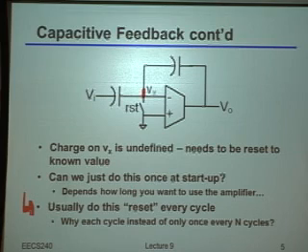So you don't have any residual effects from a last sample? Okay, you said so that I don't have any residual effects from the last sample. That is true, but let me be a little bit more explicit to make sure it's clear. By the way, this particular thing may or may not exactly get rid of the effects of the last sample. It will get rid of it on this Vx node. It may not get rid of it everywhere else, which we'll come back to in 1 second.